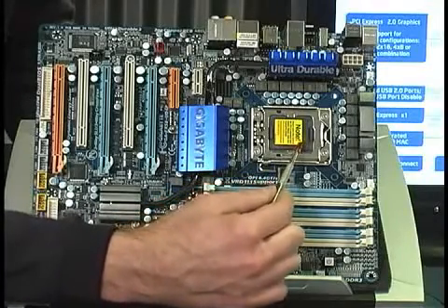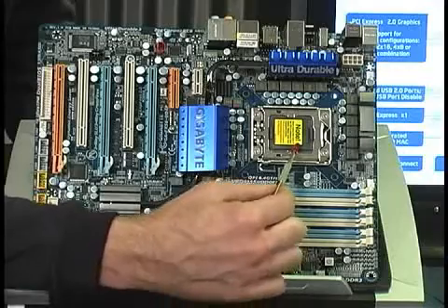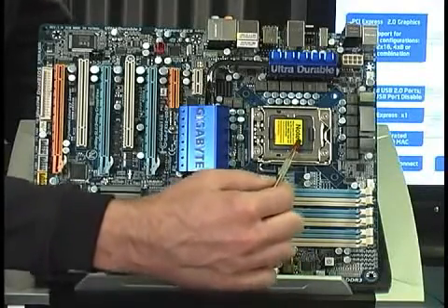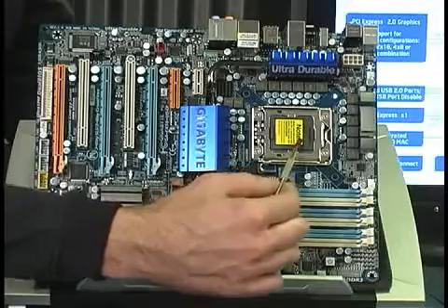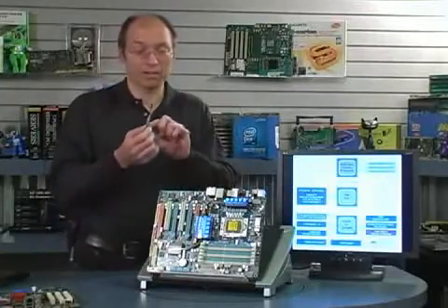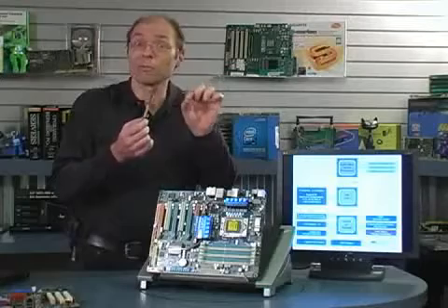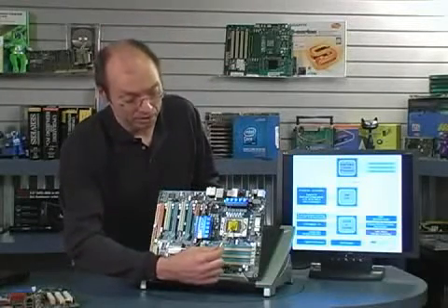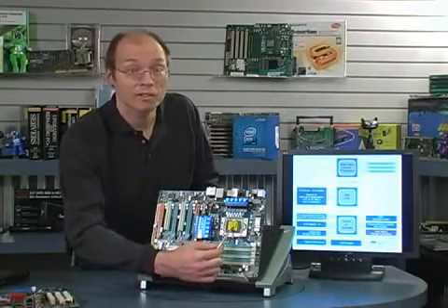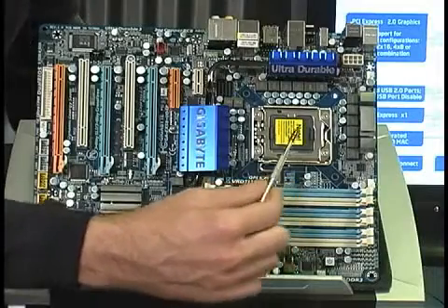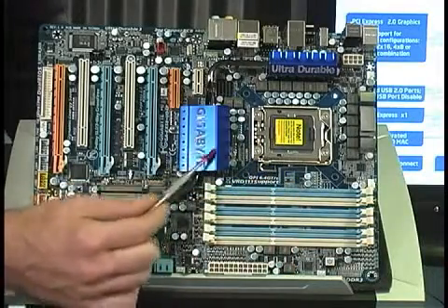See, the little pins are sticking up from inside the socket, and if you were to touch them with your finger or snag them with a piece of cloth, you'd bend them and possibly render the motherboard inoperable. The processor itself doesn't have any of the pins. It just has lands. It just has basically gold spots that make contact with the pins when it's inserted. So you'll see these protective covers, and I recommend not removing this cover until you're ready to directly install the processor. The North Bridge component is right here in this case.